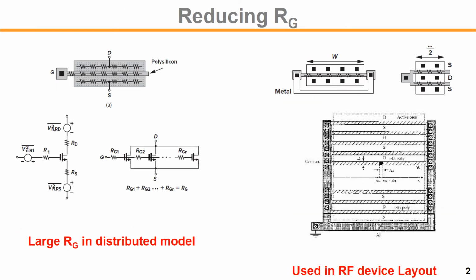If you look at the physical layout of the transistor, we can draw it like that. For example, the poly resistor is quite large if you use a single poly like that. Also we have drain and source diffusion resistors. The diffusion area also has finite resistance. So we can model those gate, source and drain side resistors. All those are noisy sources.